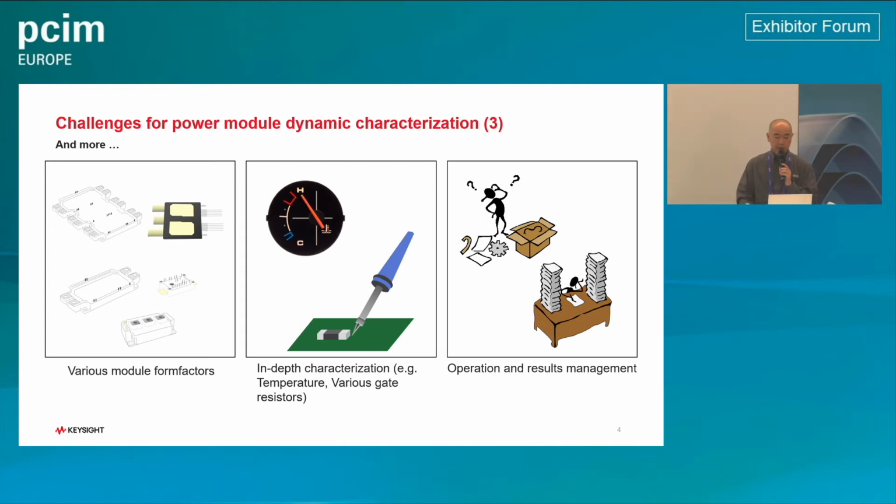And to make the in-depth characterization, the thermal dependent measurement or temperature dependency characterization or characteristics with various gate resistors should be included. But both takes long time to perform the test.